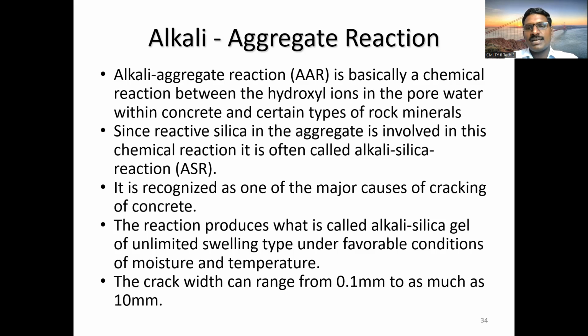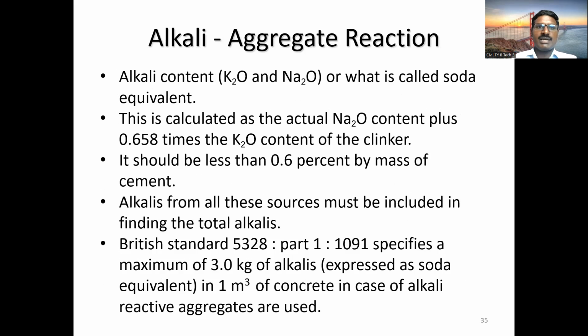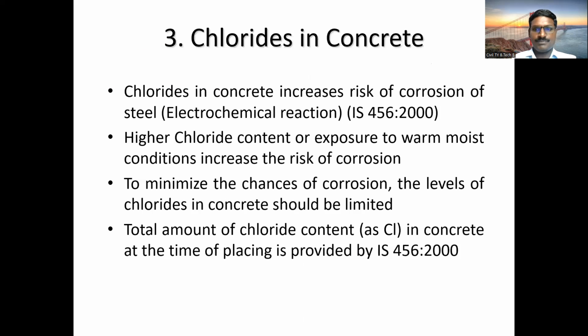So these alkali aggregate reactions cause the cracking of the concrete, with factors such as the conditions of moisture and temperature, and the crack width can range from 0.1 mm to 10 mm. So this will happen due to this alkali aggregate reaction.